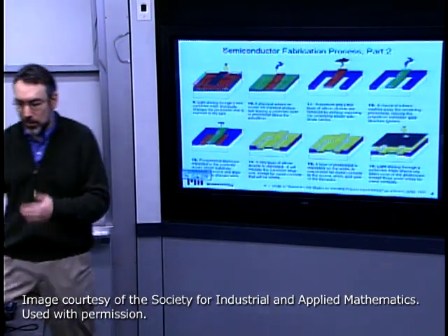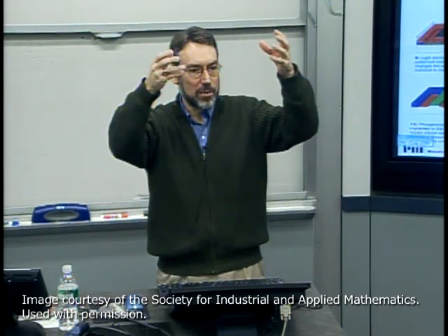In this case, we use typically a chemical vapor deposition process, again in vacuum equipment, but we decompose silicon dioxide carrying molecules in a gas plasma. So there'll be a more complex molecule typically coming in, and we decompose that, and basically it snows on the surface of the wafer and builds up a silicon dioxide layer.